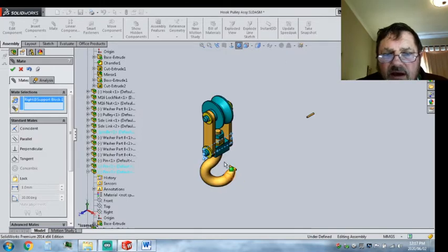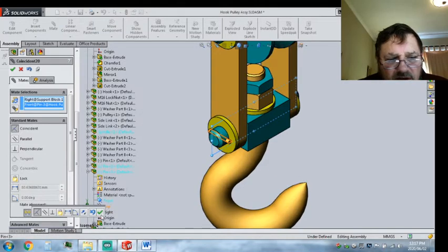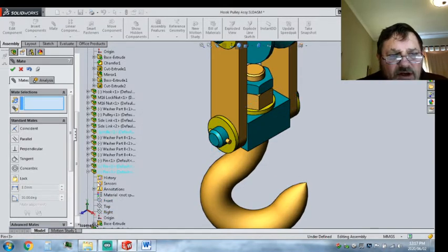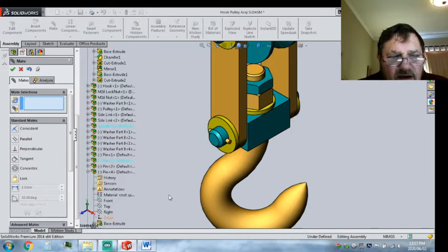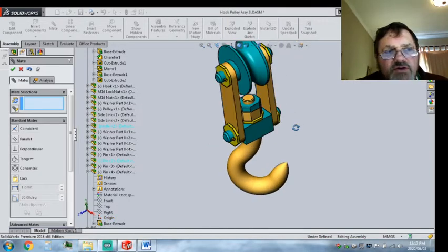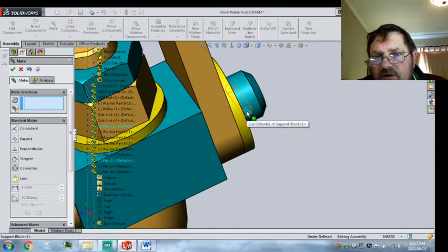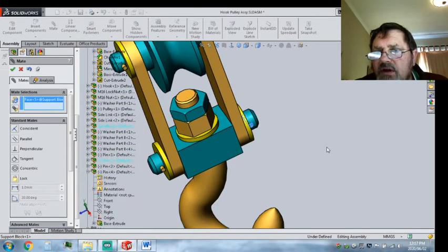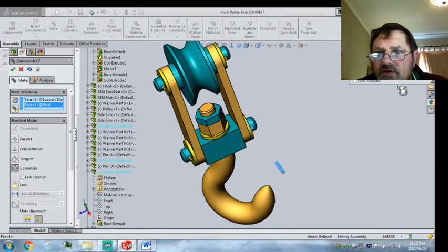Isometric here. Zoom up here. And let's go look at his front plane. Yeah, his front plane works out correctly. So you've got to manage your screen a bit. Close that key up. Open that key. We're ready for the next one. So now we're going to go choose, not the edge, zoom up, but more there. Choose that surface. And pin number 4, we can choose that surface.